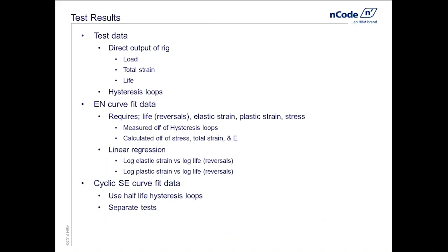Because we're interested in plasticity, we need to have stress-strain behavior as well. Many times, especially for moderately low to high cycle behavior, plasticity is done inside of the fatigue program, which means we have to have the stress-strain curve there to do our fatigue calculations. If we're at very low lives, we need to do the plasticity in the finite element program, but we still need to have stress-strain behavior there as well.